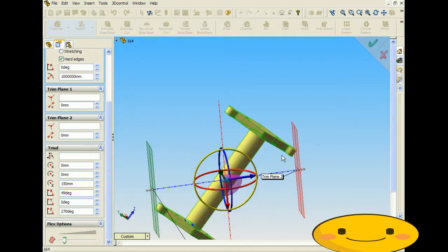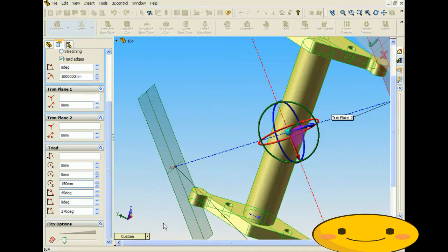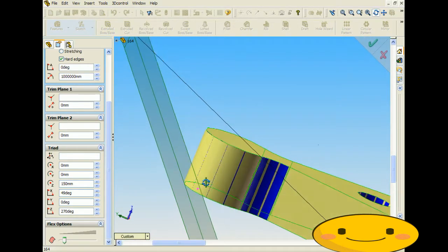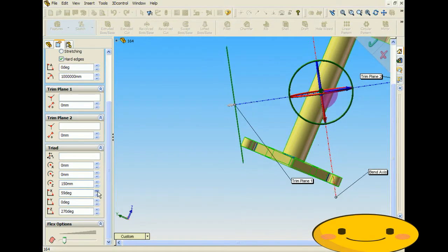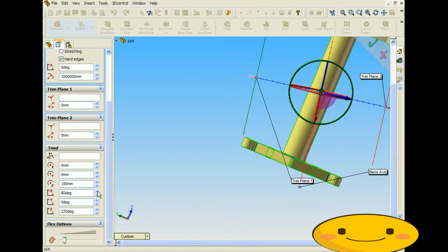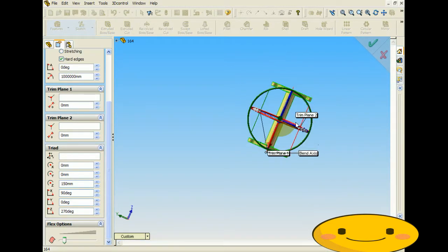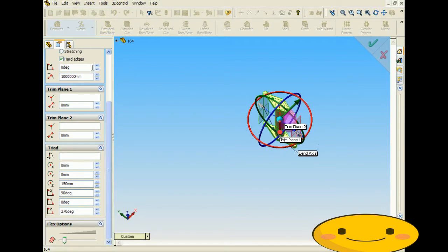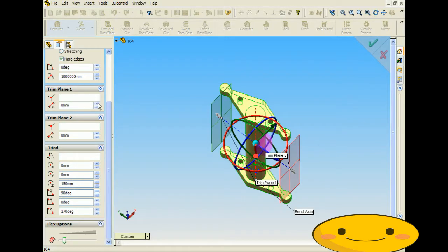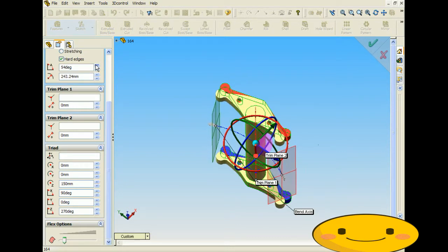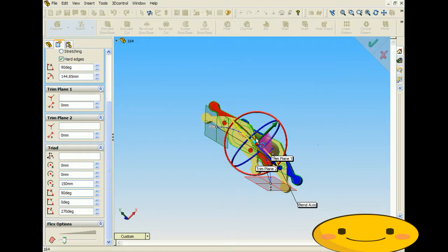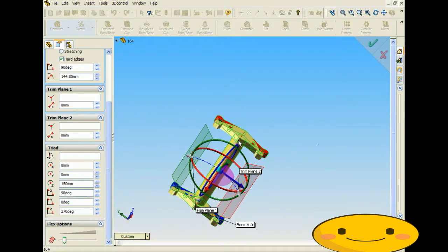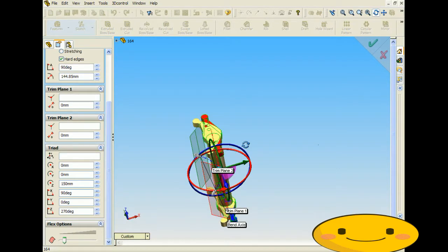As you see, as I'm rotating around, like I was saying about being tangent, when you first make it, these trim planes are always going to be tangent to a point. So as you keep going around, it's always tangent. Let's just put it to 90. Now let's add a bit of an angle and see what we get. Let's make it 90, this angle here. And you can see that we're bending. Now let's click OK.